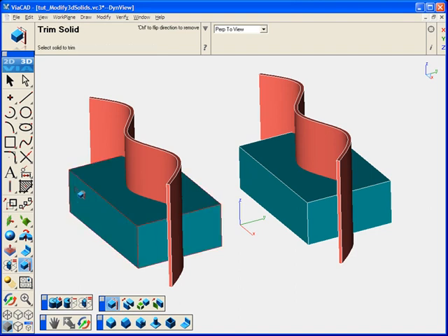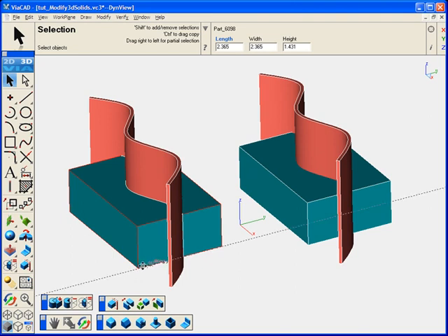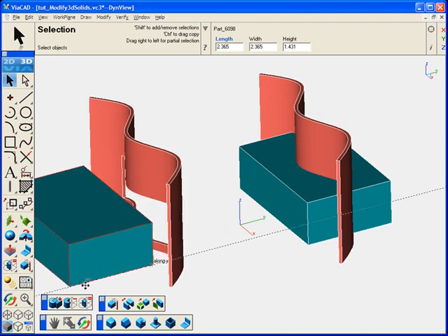First, you select the surface or the solid that defines what will be trimmed away. So in this case, we'll select the block object that defines what will be trimmed away, and then we'll click the extruded curve, and you'll see that when I drag the block out, the profile of that has been removed from the extruded curve. Now we'll undo.